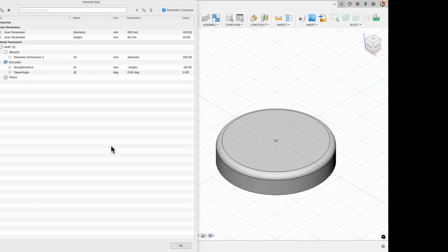So here's some of the extra power of parameters. There's a general thing in 3D CAD where one thing controls another thing. One thing is driving, the other is driven. And these relationships give us a lot of power in our design to control it. One of the driving and driven relationships is going to be by putting some math instead of just a number. We're going to put some math so things depend on each other, or they have some relationship.